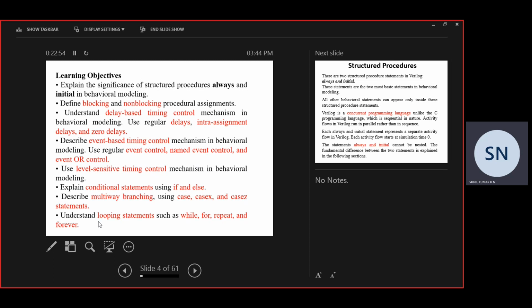That means, until you run the simulation, the clock will keep generating until the $finish statement is reached. So it is going to execute for that simulation. If you are using forever and you are not using $finish, then normally the simulation will not end. It will be an infinite loop. That means until you terminate, until you exit from the program, it will keep on running. So in that statement, if you write a forever program for clock generation, it will run until that time.